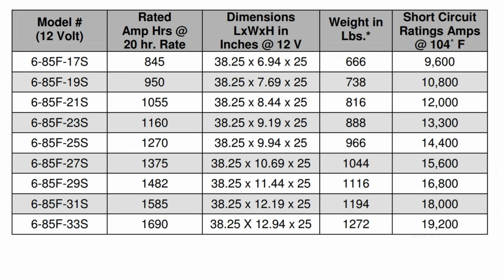Ultimately, we did not go with a 2-volt battery or 6-volt battery. We went with a 12-volt battery, 8 of them. What we ended up needing was around a 120 kilowatt-hour battery bank.